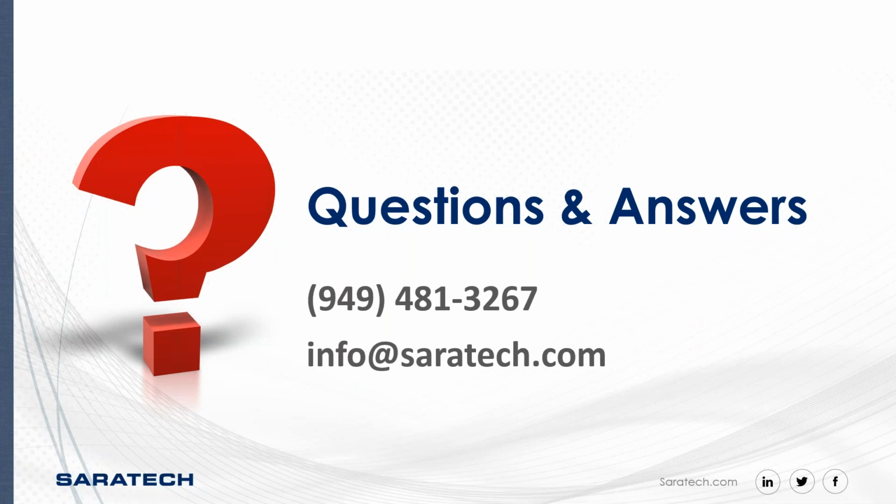And the final question is, once a standard part library is added to NX, can more parts be added to the library folder? And will these updates be reflected in the NX library? Yeah, absolutely. So once your library is uploaded to NX, you can still always go ahead and create new standard parts, just as I showed in the presentation. And you can add those to your local standard parts library folder. And then you can go into NX and just right click on your library and hit a refresh button, and it'll automatically update and include any new parts that were added.